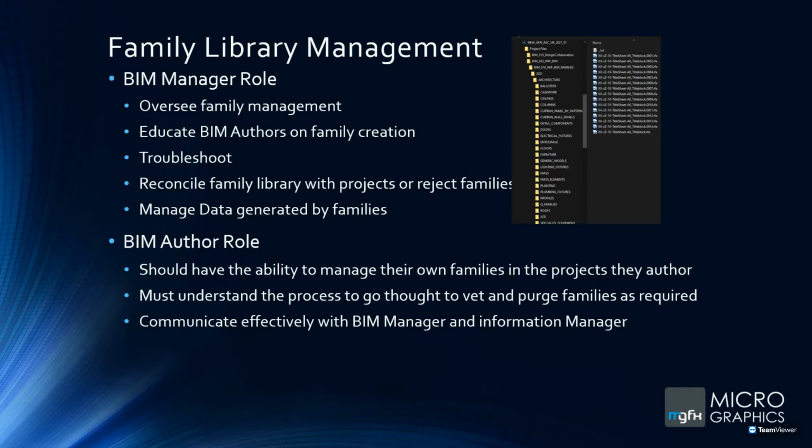Okay, and then very importantly also is the data generated by the families. So data can take many forms. Typically what our production processes would be interested in would be schedules, how much of what there is, but it goes much further than that, because the embedded data within families maps onto further downstream, where the design models are used during construction, and then ultimately in facilities management, where the metadata that is attached to the families is used.